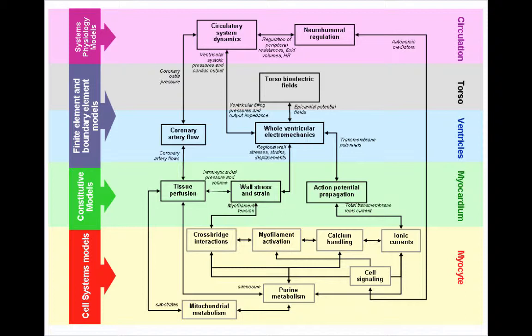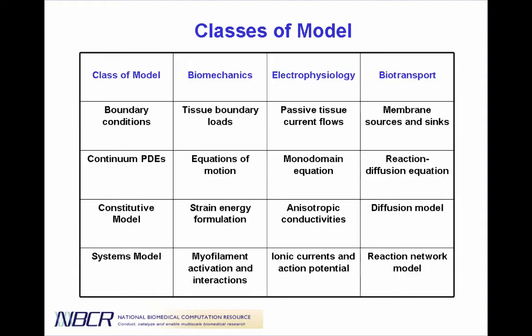At its core, Continuity is a PDE solver that implements finite element methods for nonlinear mechanics, reaction diffusion, and monodomain problems. A typical multi-scale problem in Continuity spans 3 or more scales, typically comprising a system of ODEs at each point in the physical domain, representing a network of biochemical or biophysical interactions, a constitutive law representing physical properties of the system that spatially couple these pointwise networks, a system of PDEs representing the conservation law governing the physics over the anatomy of the system, and a model of boundary conditions representing the interactions of the system with neighboring structures.